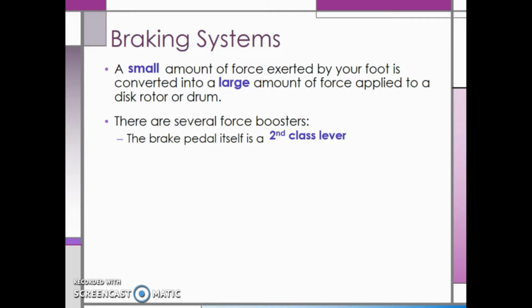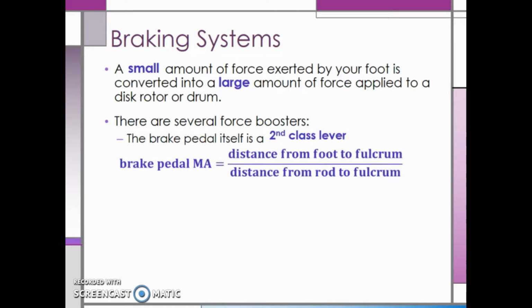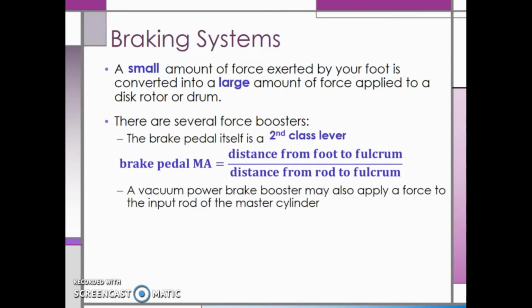We can find the mechanical advantage of the brake pedal by taking the distance from your foot to the fulcrum divided by the distance from the rod to the fulcrum. A vacuum power brake booster may also apply a force to the input rod of the master cylinder.